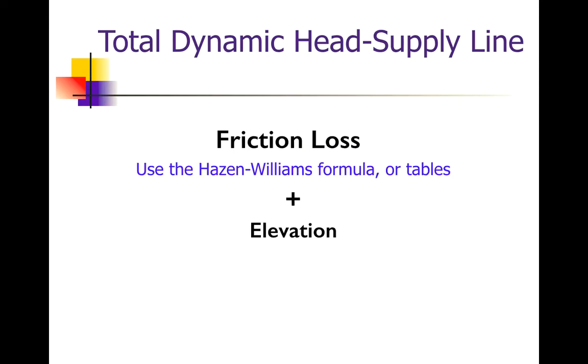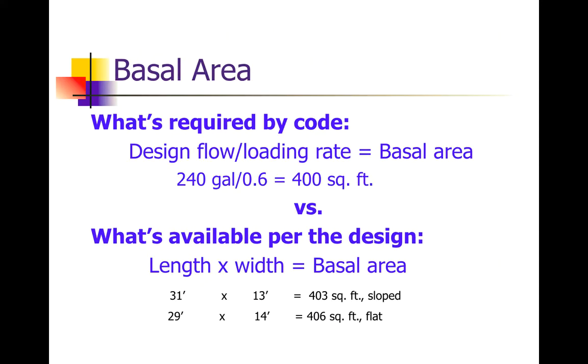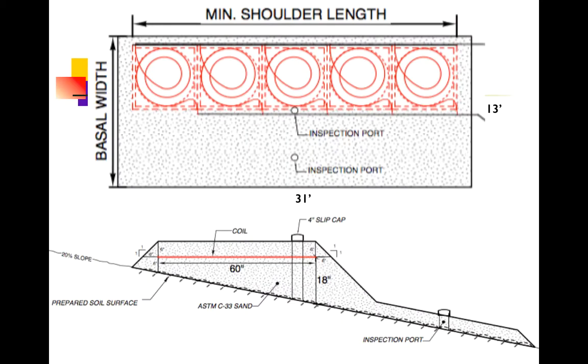Go back a few more slides. For instance, on this downslope slide, you could cover that toe with soil. You could also backfill around the upper side, around the sides to even out the slopes. That would be appropriate. We want to keep the minimal amount of cover over the top so it's easy for plant growth to get in and take advantage of the nutrients and moisture that's going to be present around those coils.